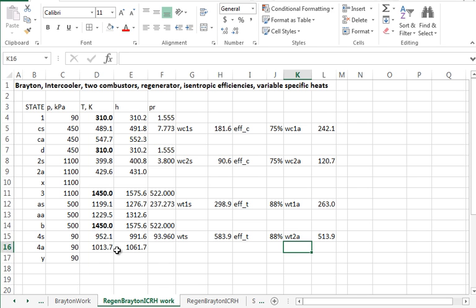Okay. All right, at this point, we have 4 as the outlet from the second turbine, which goes into the regenerator. So if you look at your illustration, you say, I have some hot fluid coming in the hot stream of the regenerator, and I want to transfer as much as possible. Well, what's the maximum that can be transferred?